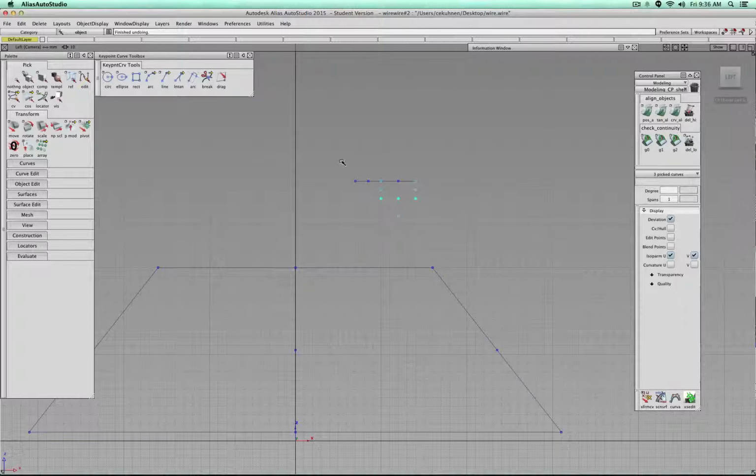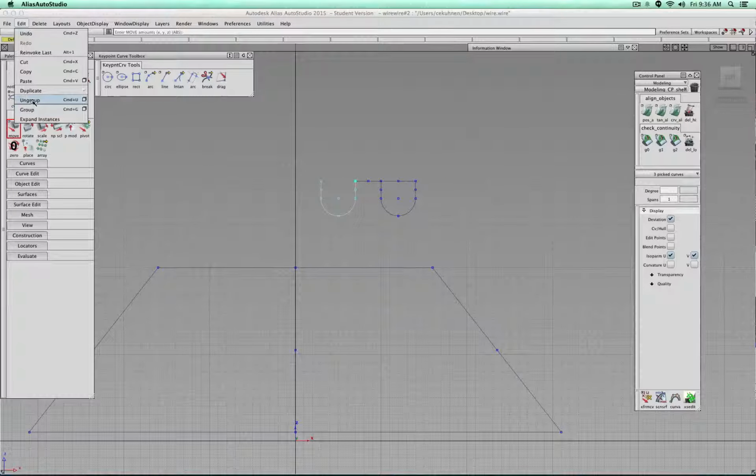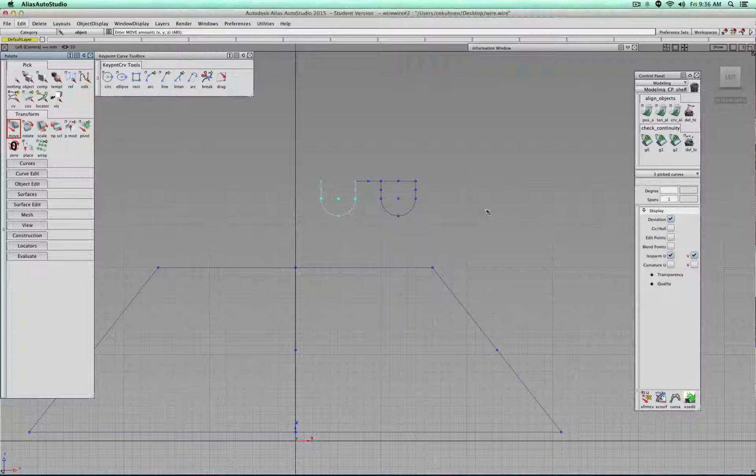So what I'm going to do now with those objects selected, I simply can go to group. Now it is a new group. The group has its pivot point always at the center down there at the moment. So I'm going to, maybe I don't have to, but I'm going to recenter it to there. So I can easily, middle mouse button, snap it to where it needs to be. And then I can go and ungroup and I'm back. So instead of resetting the pivot point for all curves, then because it's reset, I can simply create a group and I'm good. So this line I don't need anymore.